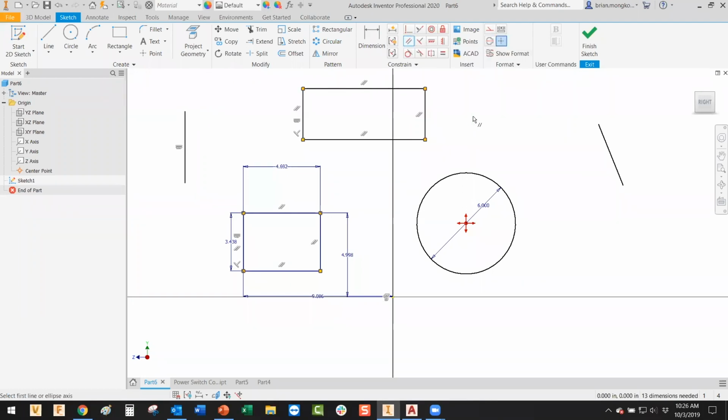And when fully dimensioning your sketches, like mentioned earlier in the best practices, you do want to use a lot of these constraints. These help to define and put your sketches in place so it doesn't move around, but it also gives it relationships to each other and about the origin as well. So it really helps to make your models and sketches more predictable and behave more intelligently as much as possible. So whoever else is taking a look at this sketch or 3D model later down the line can understand your models better.